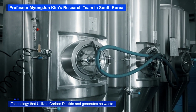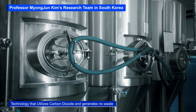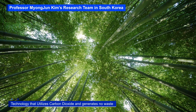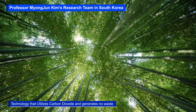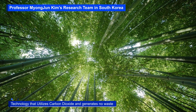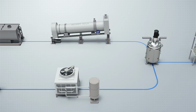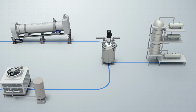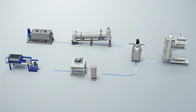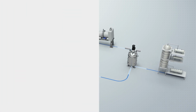Most importantly, this technology does not generate waste during manufacturing. Furthermore, it utilizes carbon dioxide, making it an environmentally friendly technology that can also secure carbon credits. This technology manufactures sodium carbonate using water with sodium sulfide, which is produced through the dry process of reduction roasting, and carbon dioxide gas from sodium sulfate.